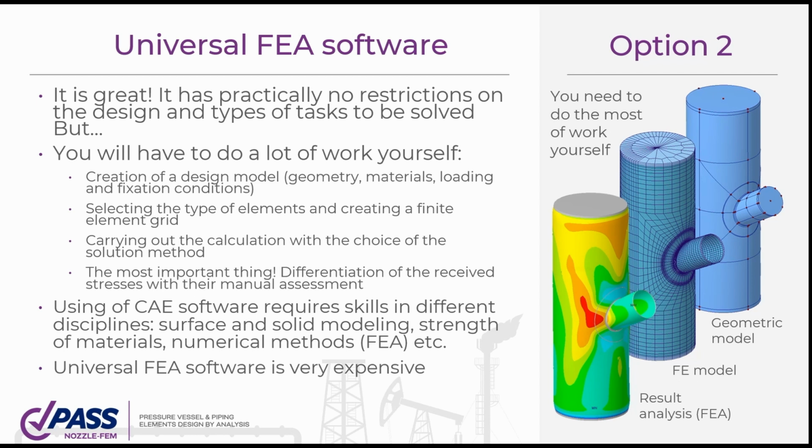After that, you need to select the type of elements and create a finite element model, carrying out the calculation with a choice of solution method. But the most important thing, you must differentiate the received stresses and evaluate them. Using FEM software requires skills in different disciplines: surface and solid modeling, strength of materials, numerical methods, and at last, universal FEM software is very expensive.